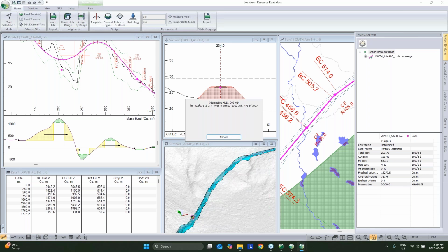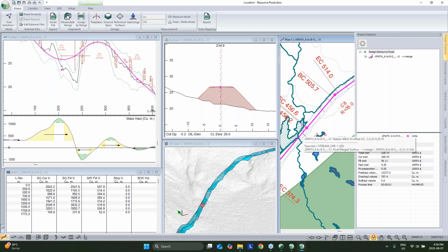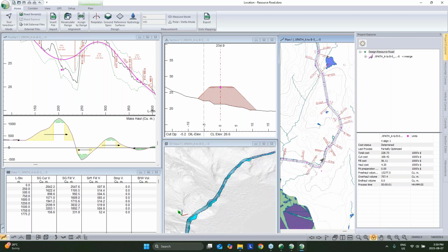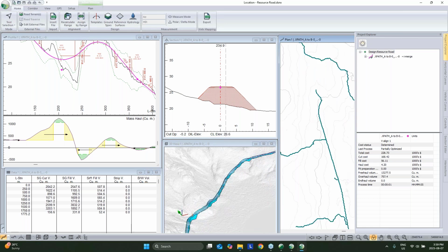It's going to calculate where there would be ponding and where your streams would be. But since we don't have culverts yet, it's also showing us the ponding against our road and giving us a pretty good visual aid, at the click of a button, on where we should put those pipes. So ponding, really important. The next thing that it's doing is it's using the same stream calculations that we have in Terrain. So we're also calculating streams that exceed a threshold value.